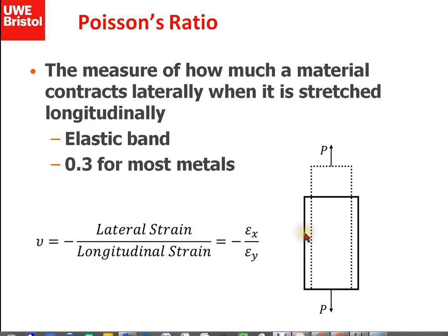What happens is that the lateral strain, which is in the x direction here, will move in a little bit, and the amount that it moves in is not typically the amount that we would need to keep the total volume the same. So when I pull this apart in the y direction, it moves in a little bit, but not typically enough to match the initial volume. Okay.